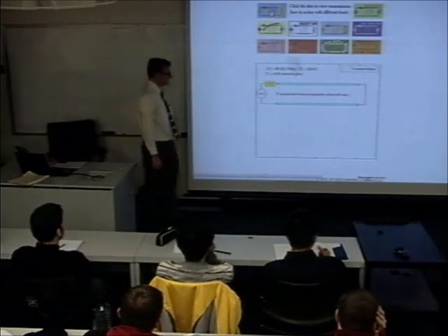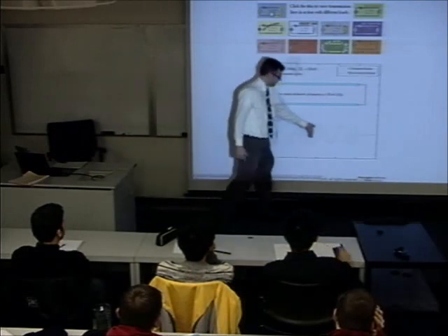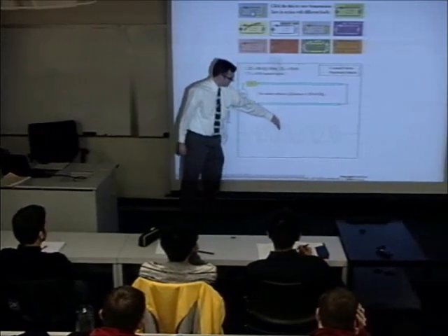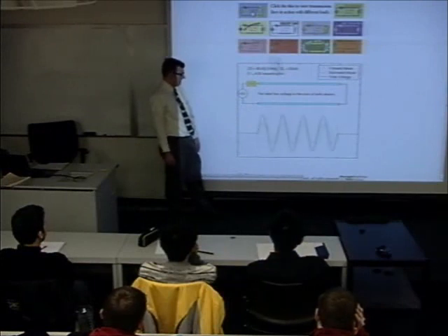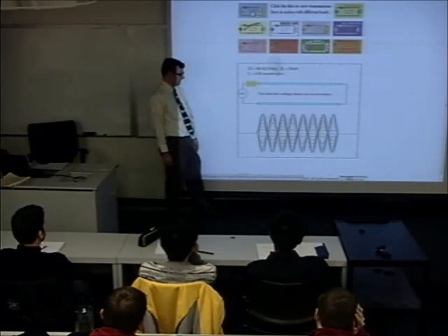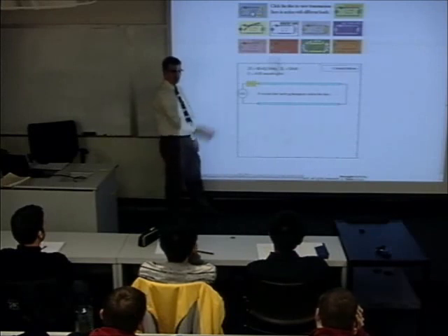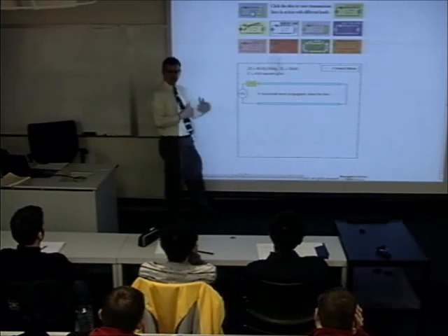Okay. Now, what happens if you have a short circuit? This is a case that we studied. The forward wave goes back. The backwards propagating wave is this red dotted waveform, and the sum is a standing wave. What is the envelope of the standing wave as a function of space? It is not constant on the line. It's actually those humps where you get peaks that are half a wavelength apart, and peaks and nulls that are a quarter wavelength apart. Let's take a look at that again.